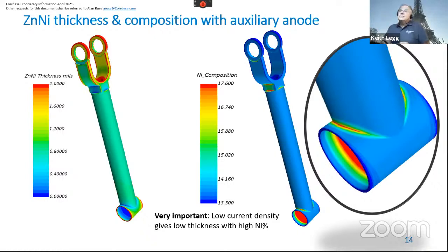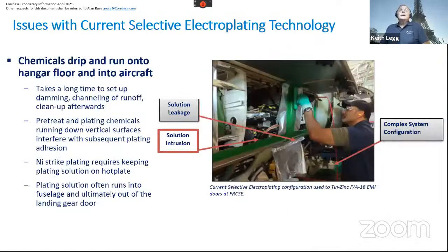And in that case, you can get stress corrosion cracking, and the whole thing breaks. So you really have to keep not just the thickness, but the chemistry correct everywhere. And that means you really have to take very careful care over it. You can no longer just chuck things in a bath. You now have to do very careful design of all your tooling, which is done computationally. Okay, next. Yeah, thanks for pointing that out, Alan.